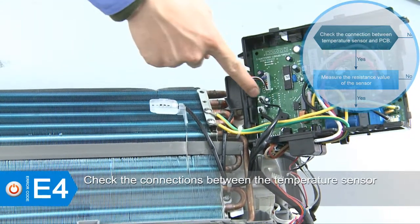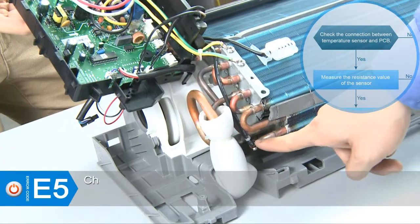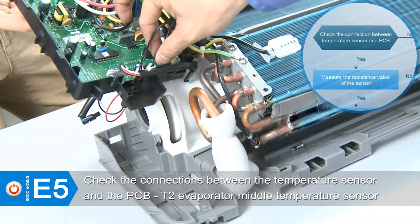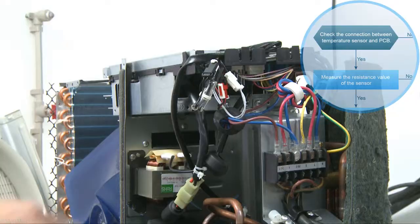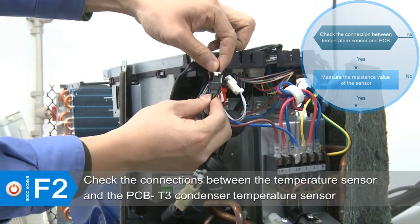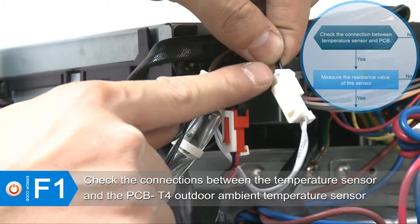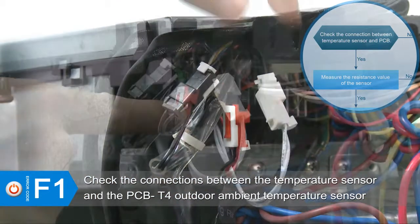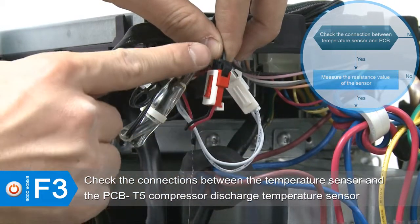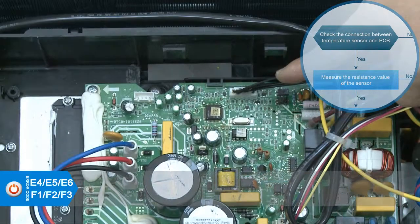This is T1, indoor room temperature sensor. This is T2, evaporator temperature sensor. This is T3, condenser temperature sensor. This is T4, outdoor ambient temperature sensor. This is T5, compressor discharge temperature sensor. Check the wiring of the sensors for different main boards.